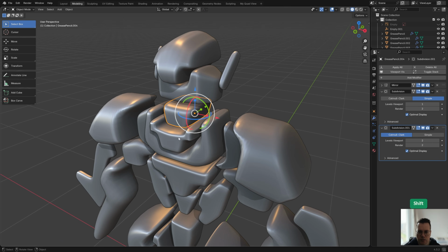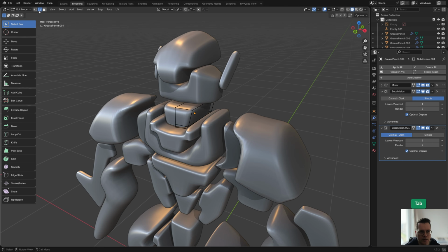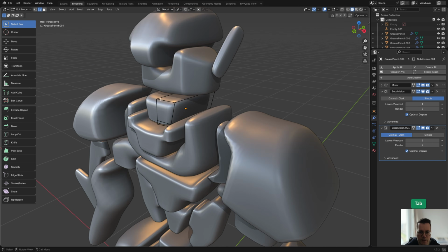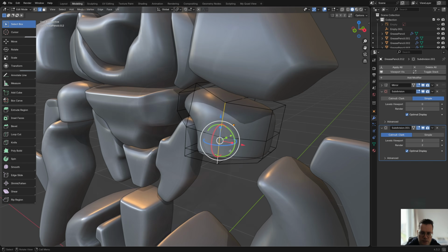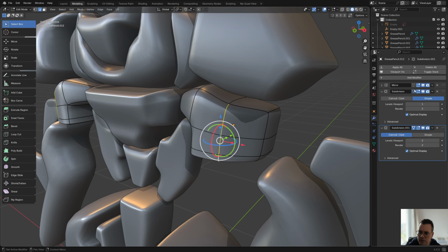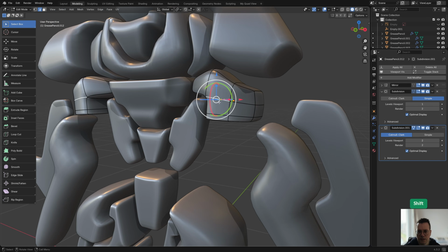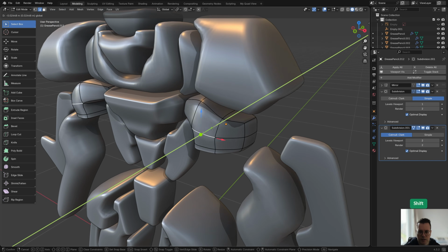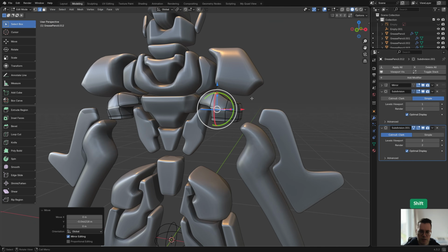I'm just quickly going to go through all of these objects and in edit mode, adjust the shape to make it more interesting. So another thing, if you think it's annoying that you have such a big difference between this cage, which is just the object, the way it looks without modifiers, and the blobby shape of the subdivided mesh, you can always enable here this button. This is the on cage button. And I'll just show you on this one as well. And so now you can see exactly what the modifiers are doing, even in edit mode. So that can be more convenient.